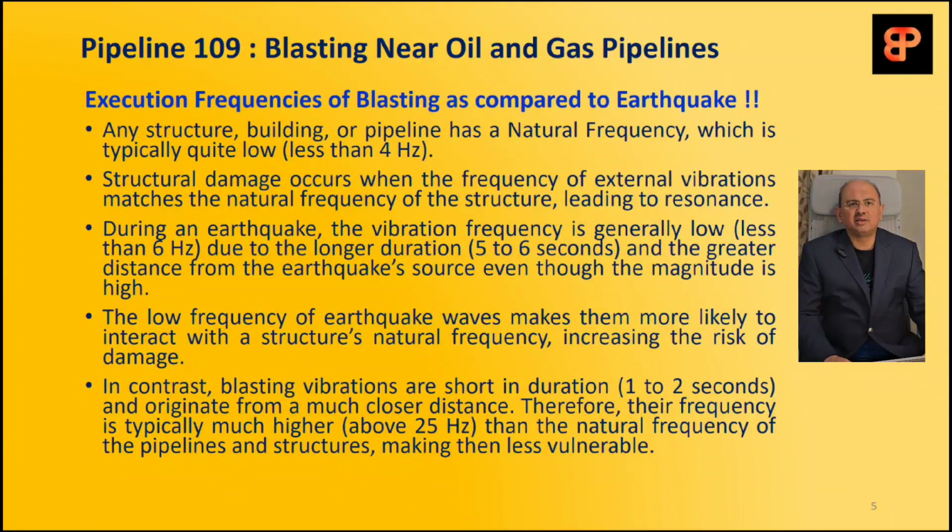Excitation frequencies of blasting as compared to earthquake. Any structure, building or pipeline has a natural frequency, as you are all aware, which is typically quite low, lower than 4 Hz. Structural damage occurs when the frequency of external vibrations matches the natural frequency of the structure, leading to resonance. So that means the induced frequency resonates with the natural frequency, and then it creates a detrimental effect.